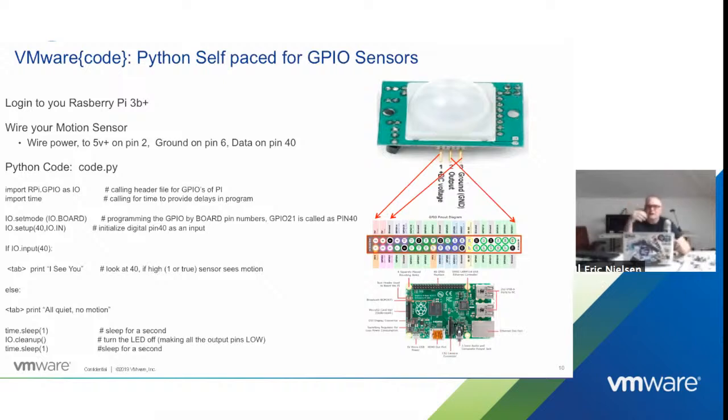Flight simulators have a frame rate, so that when I turn the joystick, you need a worst case of maybe 10 milliseconds, 10 1,000ths of a second. When I go like this, it's going to do this because I feel real. That frame rate is how often you want to go through your loop of code. You can do a bunch of stuff in that loop, but you always have to get back to the top of your frame rate.